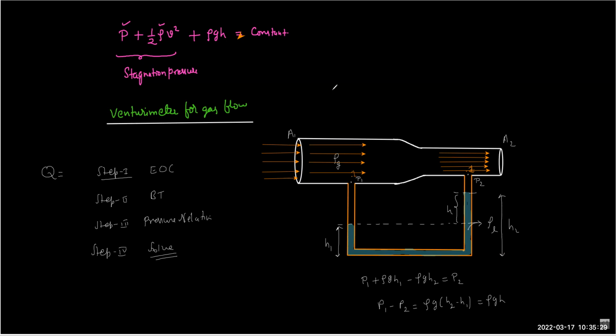So now the simple equation of continuity is what? A1 V1 equals A2 V2. You have to assume velocities V1, V2. So let's say at this cross section velocity is V1, here A2 V2. Apply the Bernoulli equation. What should we write? We can choose a horizontal streamline, right? And if I choose this as a reference, then the third term will not appear, which is good for us.